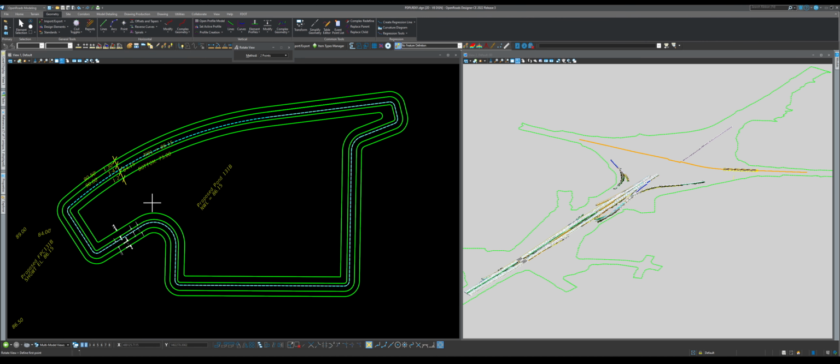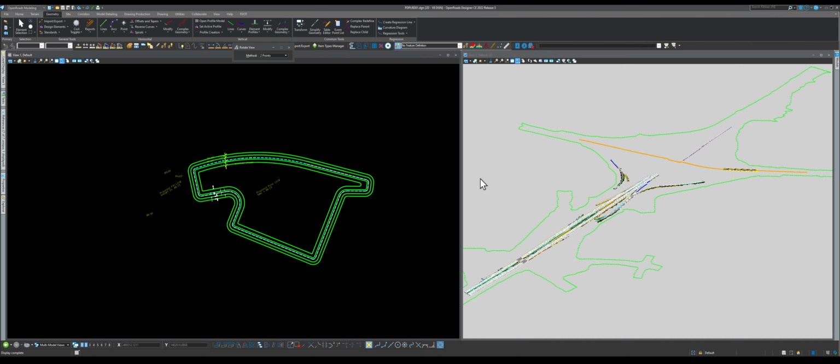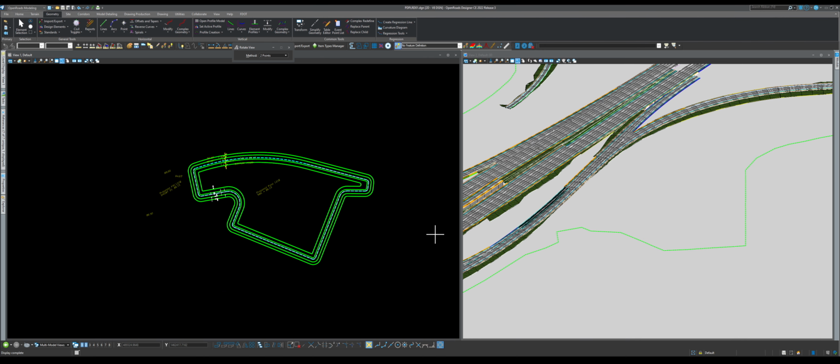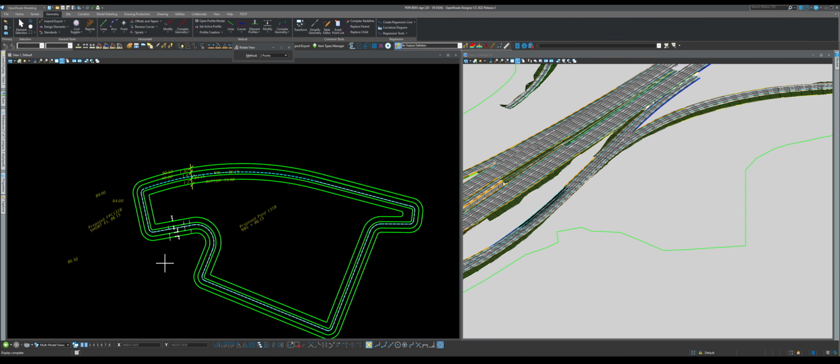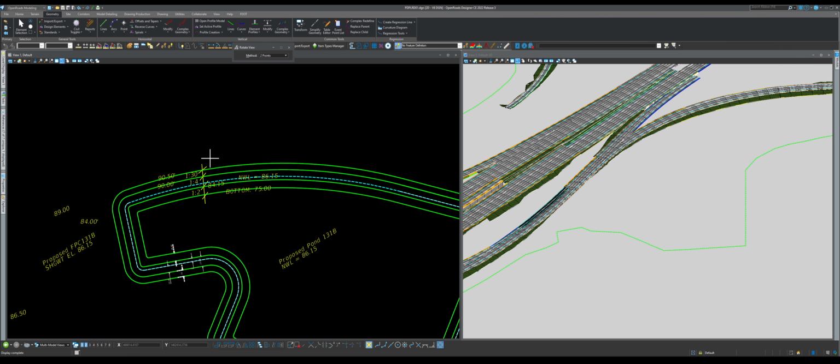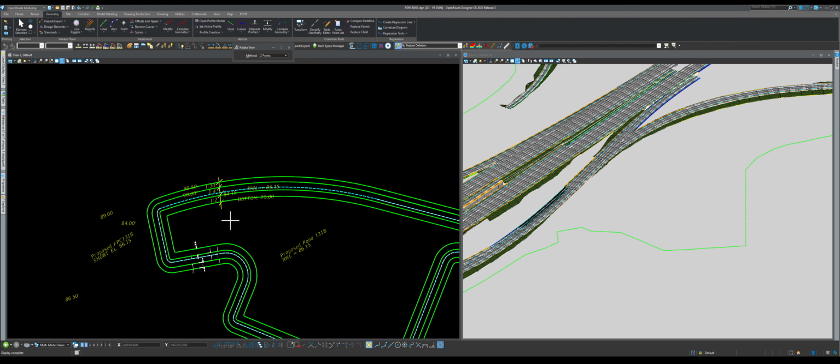So before I do the templates, I still want to do the way that most drainage people in this company do it, and I don't think it's wrong. The only thing is I think it's missing something, which I will show y'all, because by the end of this video, I will show you the template way, how to do a template in a corridor. Also, I will show you, if you still want to do it the way y'all learned, which is basically the lines, giving them elevations and then making a terrain out of those lines, there is an extra step you need to do so the roadway can connect with your stuff, okay?